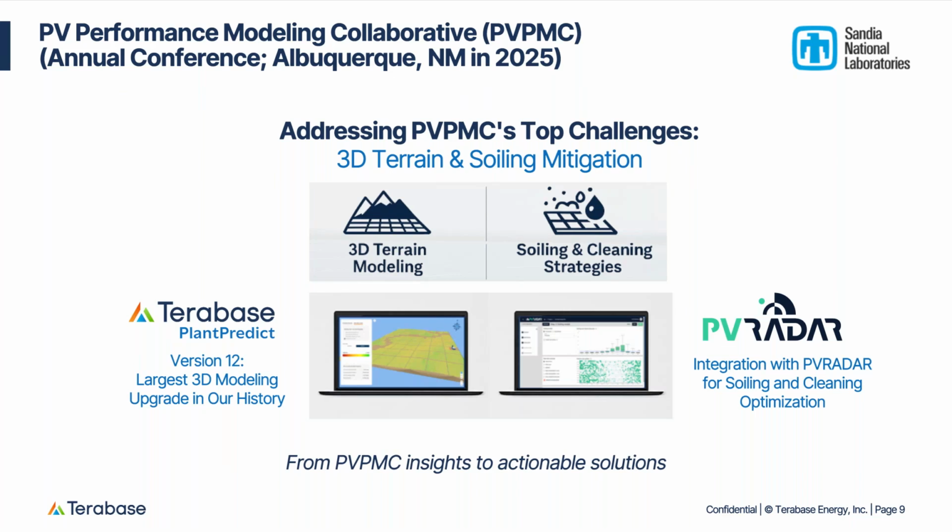And so the real challenge is figuring out how to optimize your cleaning approach so that you are most cost effectively cleaning those panels, getting as much energy as you can, but not spending more money cleaning than the energy you're producing. So doing that analysis is the real challenge.